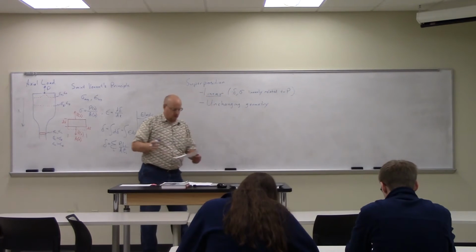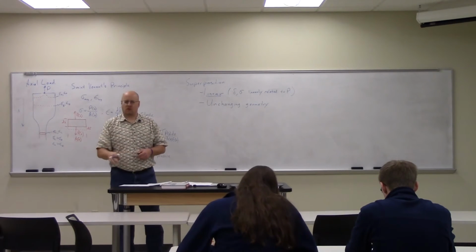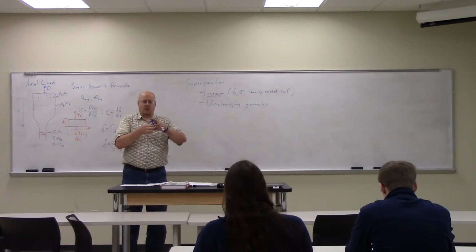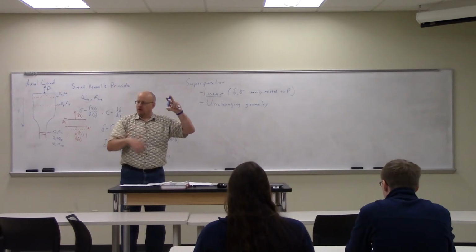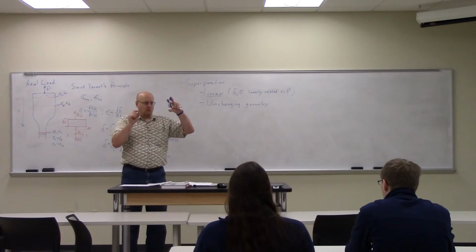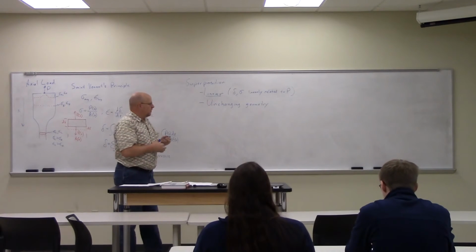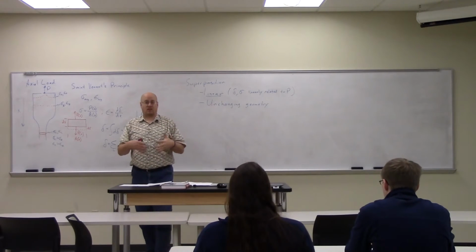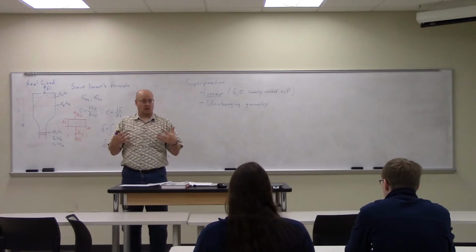Now, you look at that and say, well, anytime there is deflection, there must be a change in geometry, right? I apply even the slightest amount of load to this pen, and it compresses. Minutely, but it compresses, so it changes geometry. So here, by unchanging, we mean no significant changes, like buckling or bending.